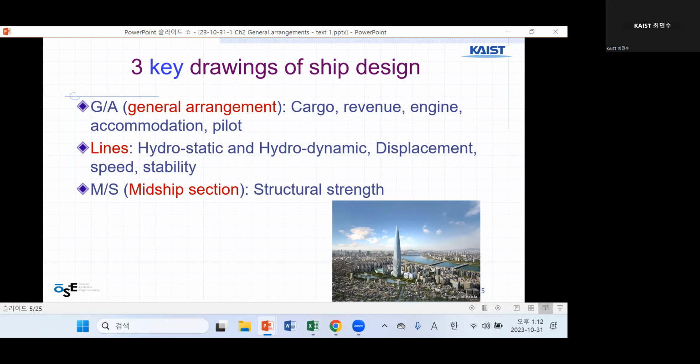And then structural strength. Probably most of the body is made of steel, I guess. Some of it is made of concrete. How do you calculate the strength? You calculate the force coming from the wind and also the weight of the building itself and people inside, and sometimes you should calculate the forces coming from earthquakes. So those things are considered to design your structural strength.